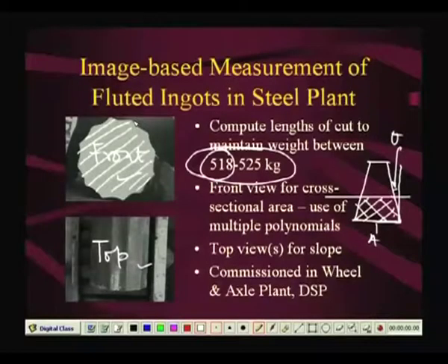So, we did that. I can tell you that this is a 2-dimensional signal processing because it is an image, and there are various kinds of estimation involved. For example, you have to have a very accurate estimation of the edge. We must remember that in these algorithms, if you make an error of 2-3 pixels, a pixel is one picture cell, then you can have a half a kg to 1 kg variation in the weight of the ingot.